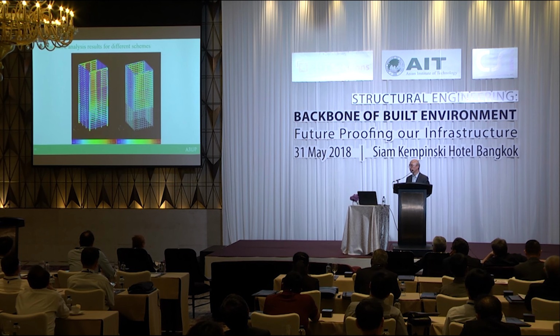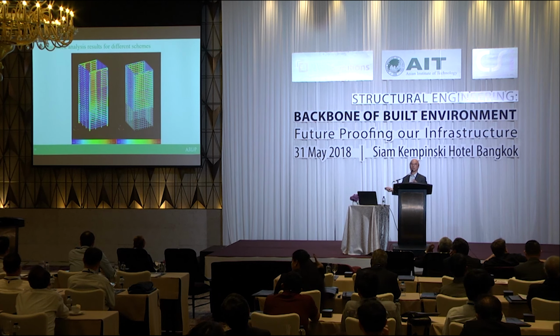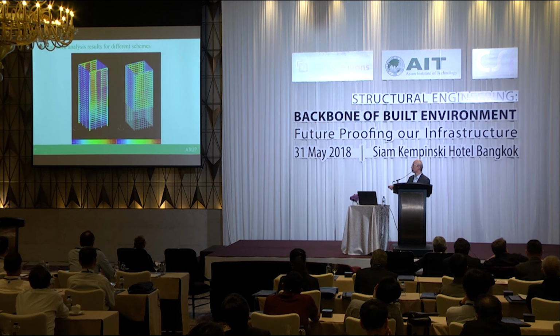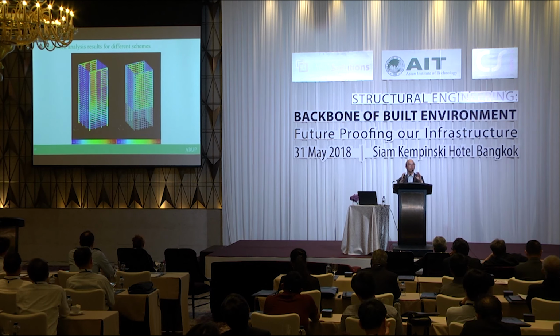So what we do is we do a couple of models, and we can calculate, see, this is the virtual work analysis. It tells us the hottest color means that it takes more force, it's more effective in controlling the lateral drift of the building. You will see that this makes sense because the top part of the building is controlled by the external frame or the perimeter.